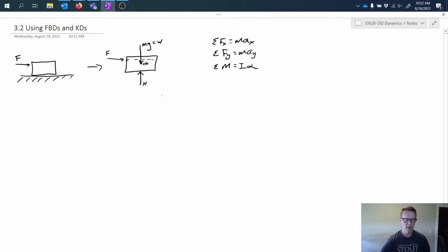It's shown on the free body diagram. Now, if we want a graphical representation of the right-hand side of this equation, we could set this equal to, graphically speaking, a kinematic diagram. The kinematic diagram is effectively the same thing as the free body diagram, except that instead of applying forces, moments, and torques to the object, we're going to try to designate how it moves. So in this case, I might say I have some forces pushing on this, and it is going to move to the right-hand side. I have the possibility of some rotation,